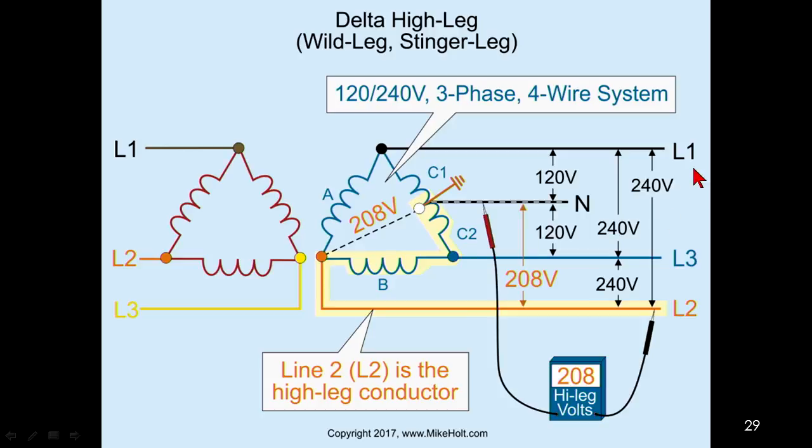I get a 3-phase load, line 1, line 2. Okay, well, then that's going to give me some loads, 1/3 on C, 1/3 on A, 1/3 on B. I got line-to-line loads. Okay, line 1, line 3, that goes on phase A. I got some line 3 and line 2, it goes on phase B. When you get a delta secondary, you have to take these loads and balance them, and you have to show this configuration because your neutral connected loads can only be on C.